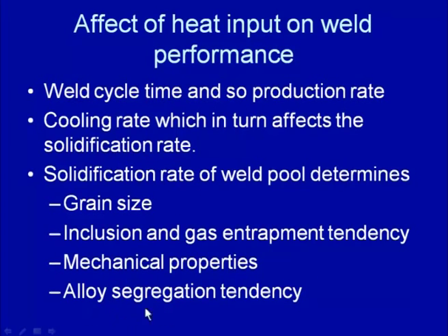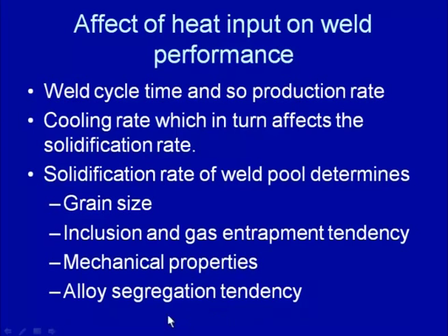While in case of a high cooling rate, less time is available for solidification, and the low melting point elements and phases will not get enough time to segregate, and that is why a high cooling rate will result in a lesser segregation tendency.